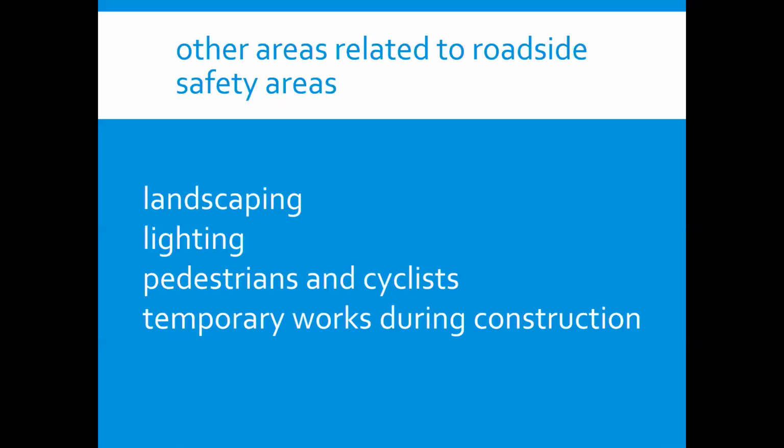Construction and maintenance operations should not inhibit traffic, and where possible, separation should be provided through diversion routes. Some studies have identified high accident rates through work zones where proper warning and delineation has not been achieved.